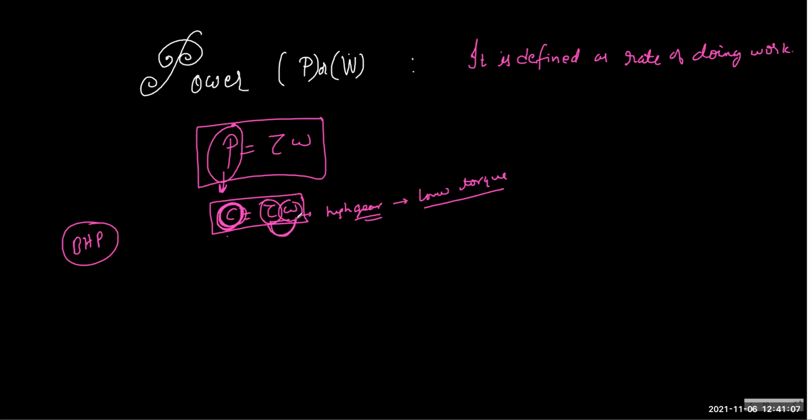On the steepest part, we go to gear 1. Why? This will produce the lowest RPM, I mean omega is least and torque is most. The torque becomes maximum. So when you're driving on low gear, the torque is maximum, which we use for climbing the slope on the steepest part.